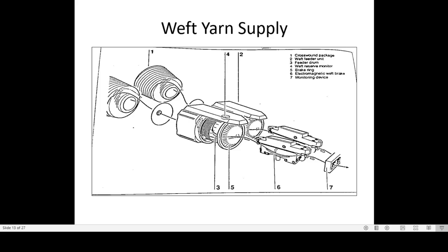So one coil will be laid, it will be pushed forward. Second coil will be laid. The first 2 coils will be pushed forward. Third coil will be laid. 3 coils will be pushed forward. So 10 coils will be laid, pushed forward, and they come in the range of this sensor. There are 4 laser sensors. When the first coil touches this laser sensor, this winder stops.